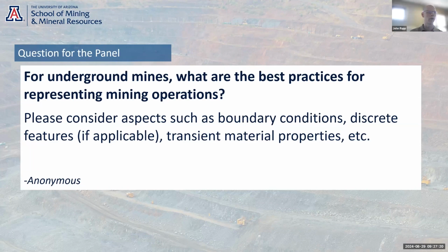Yeah, we're getting to be a bit of a broken record here on this, but it's about the monitoring too. To be able to figure out what Jeff's talking about, you've got to have a good monitoring program. And particularly during exploration, operators get a little frustrated when their operational goals are based around executing a certain number of footage, that they're going to stop and install vibrating wire piezometers in the challenging 1,000-foot uphill hole, but it has to be done. If you don't have the data to understand the hydrogeologic model, you're just not going to be able to address the underground mine hydrogeology.